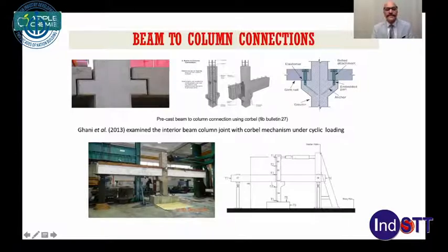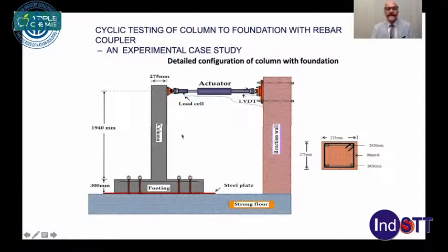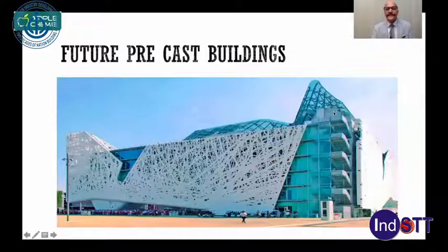And these couplers can be tested for various seismic loads and the lateral behaviors, because that is the place where they fail. So also at the foundation level, you have the couplers, get it tested. This is what you do, or rather whatever the manufacturer should do in the laboratory to ensure that the grouts and the couplers stand to the expectation, and they are designed for those earthquake parameters.